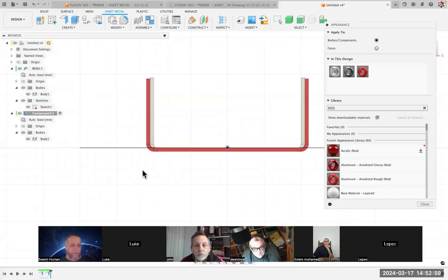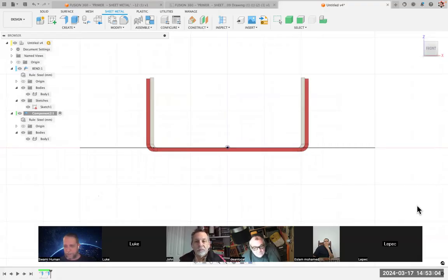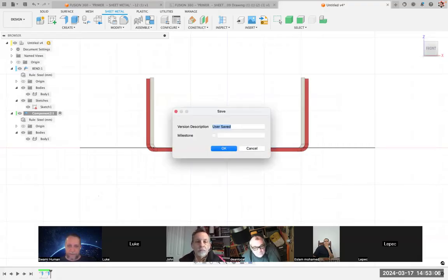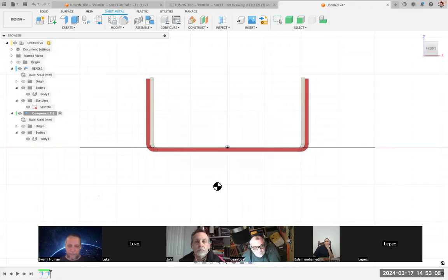Actually, that brings me to something else. So we've done that. We do our save. Like that. We have saved. Another way I could have done that, as I think about it, is to color the components. Hit Shift N as in Nancy, Shift N. And you'll see how they're now colored automatically from some color palette. So that's Shift N as a toggle.